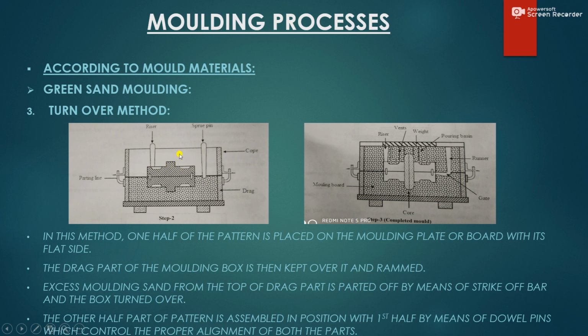Then you fill the cope portion, the upper portion of the molding box, with sand and ram it properly.